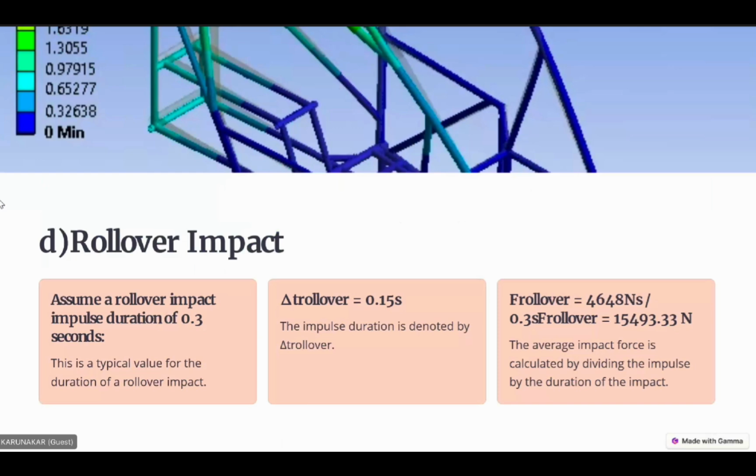This leads to the formation of brittle structures in the heat affected zone, which are not desirable, and can induce cracks after cooling. Also, it may lead to failure in case of an accident. This can be overcome by chromoly that is properly heat treated in order to extract all properties from it.